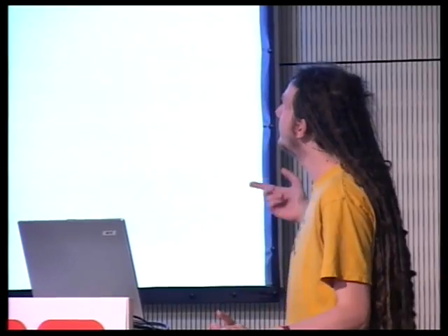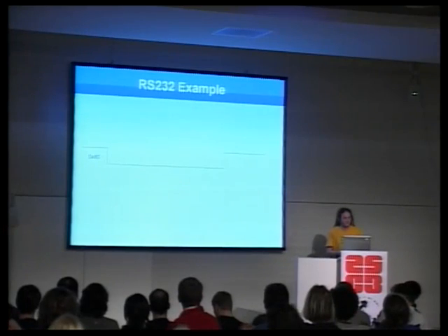Following that, we have the 3 zeros of the more significant nibble. Following this, we have a 1. That's the 1 within the 8. Following that, we have another 1 to make the number of 1s within the message even. And then we have a single stop bit. Now, 0x80 is sent before any given command frame to the bootstrap loader. Do any of you know why?